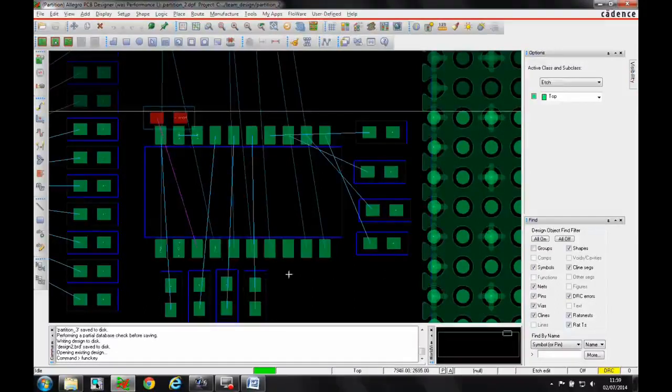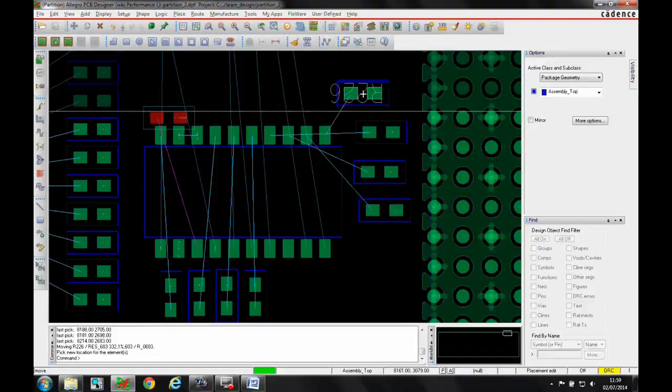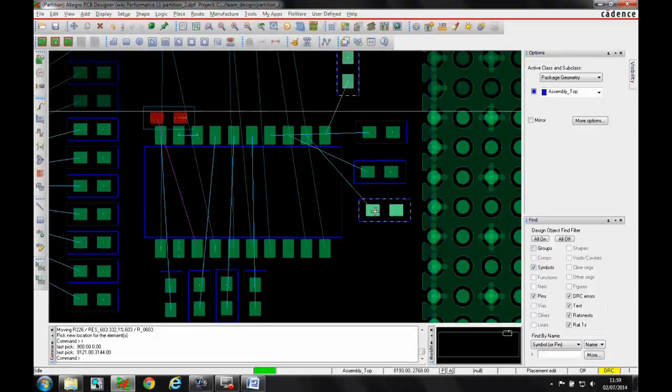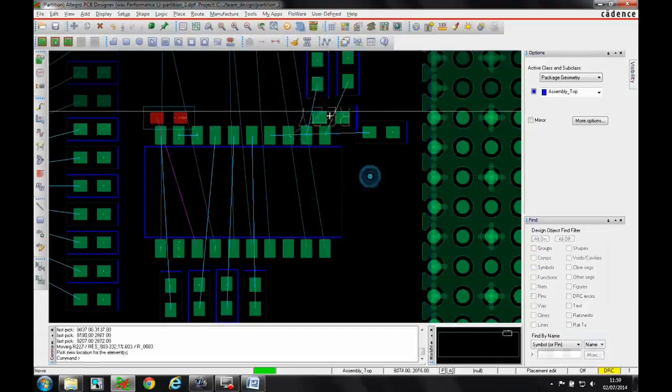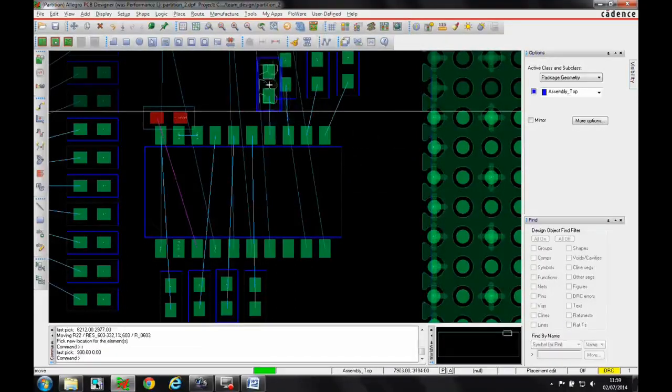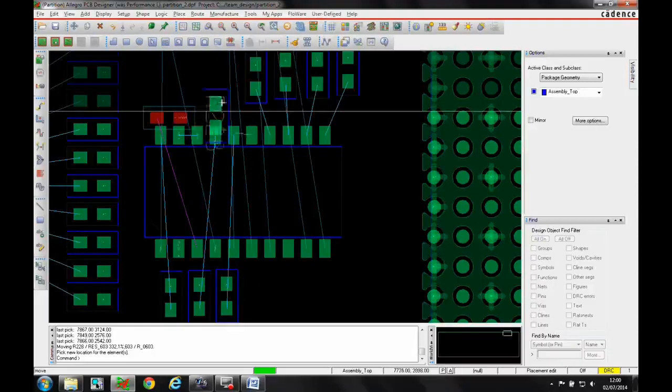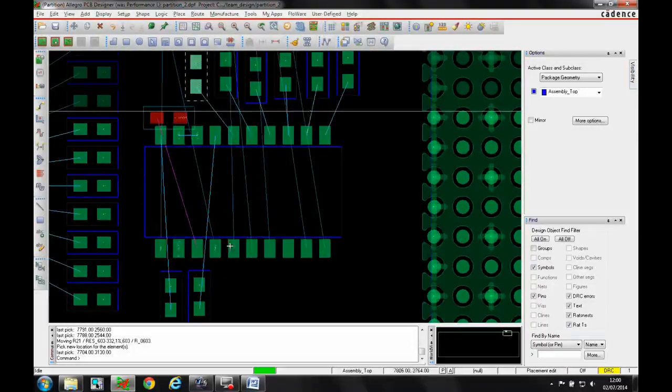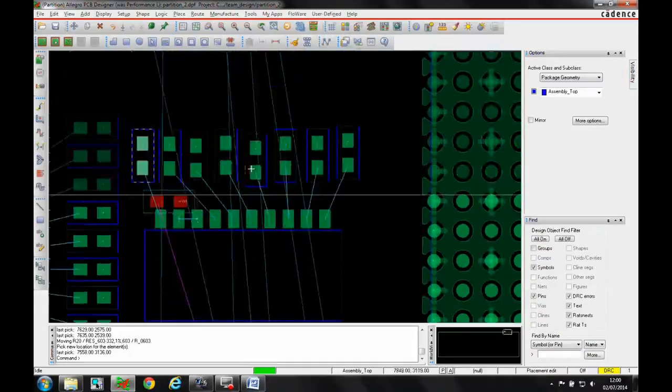So let's enable a quick function key first, and there are videos showing this kind of functionality, the ability to design a shortcut key. Then we'll go into the placement edit mode, pick a resistor, start to rotate, and move these out very quickly. All I'm doing is moving these outside of the constraint region. There's the boundary area, not the constraint region, sorry, the boundary area. We'll move them outside of the boundary area.